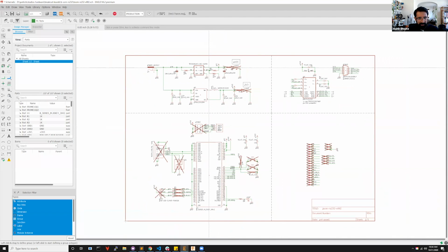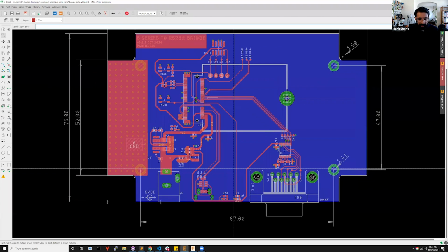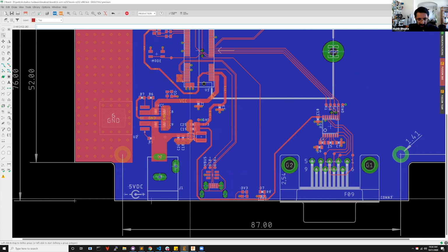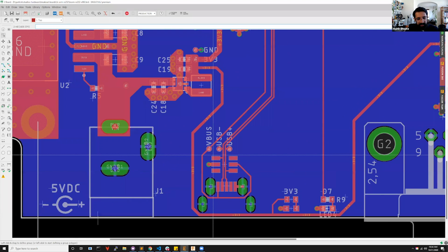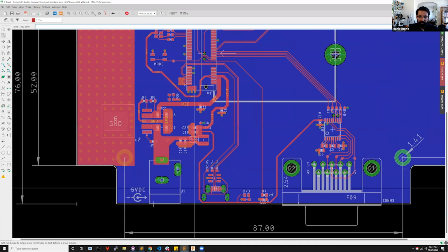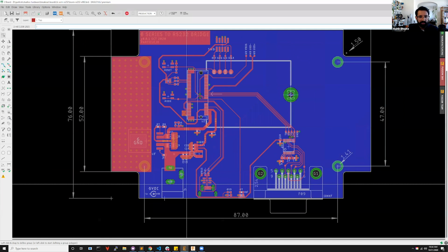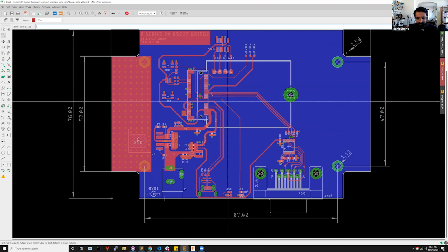You may wonder what happens on the PCB side. Well, on the PCB side, the footprints still remain there. And that would be a horrific morning to wake up to, where the footprints are missing. All it does is disable the paste layer from the PCB. So when you go into manufacturing, no paste would be applied to the parts that are not going to be populated. This visually will look good, and also give you a confirmation that those parts were intentionally not populated.